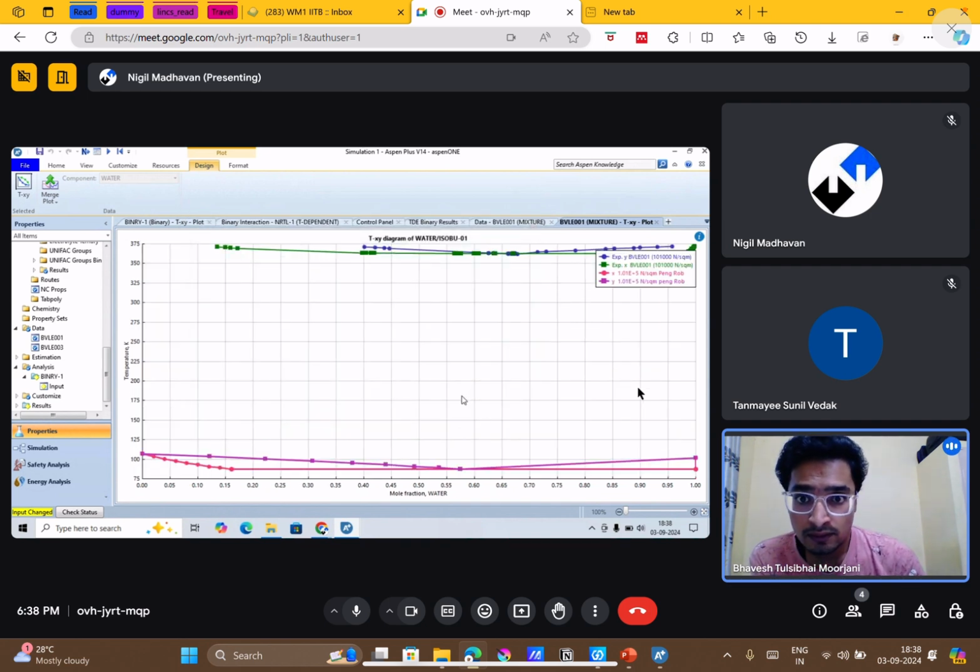Okay, so the experimental data is at much higher temperature condition compared to the water. Why? This should not happen actually. Okay, so there is much difference here. So what we will do, we will first try to fit this data. Both are at same 101. Yeah, pressure value is same. Okay, so there is a difference. So what we will try to do is fit the Peng-Robinson data such that it matches with the experimental trend.